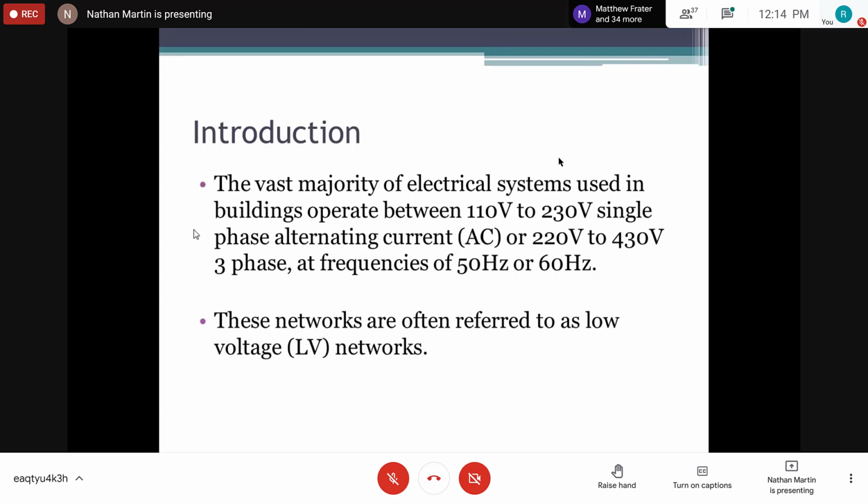So that's a critical part you need to understand about electrical equipment and when purchasing electrical equipment. For instance, if you are the design engineer at your facility, you need to take these considerations in mind: the voltage requirement for the machine, the frequency requirement, and the power requirement of the machine. You'll also look at the physical space and other stuff, but as it relates to electrical, that's what we'll be looking at.